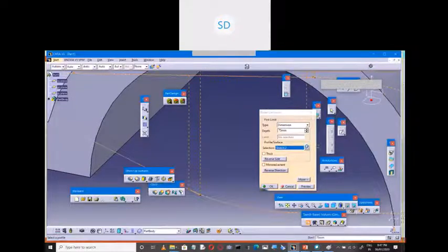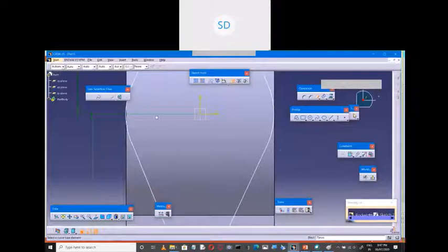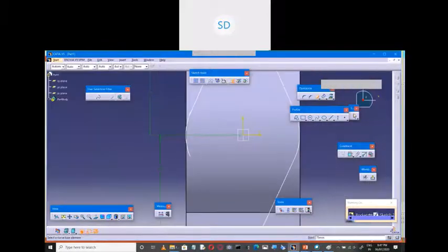Go for sketch again. Now we can just look out. Here you need to trim. Now here connectivity is not there. Then you select these two using the control key. Go for fit.